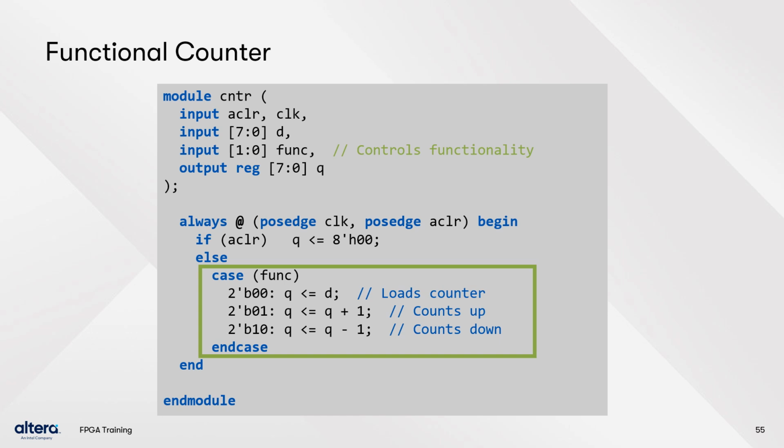Verilog does not require it to be specified. We could have specified that Q gets Q when 11 is encountered. This is completely redundant, as this behavior is implied by the functionality of the variable Q. A variable will always retain its current value until it is driven with a new value.